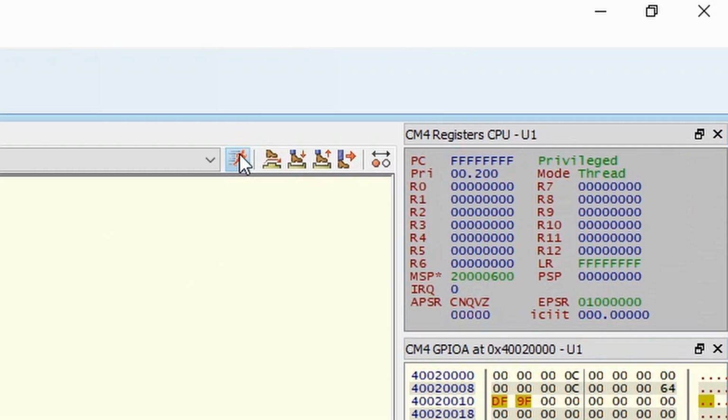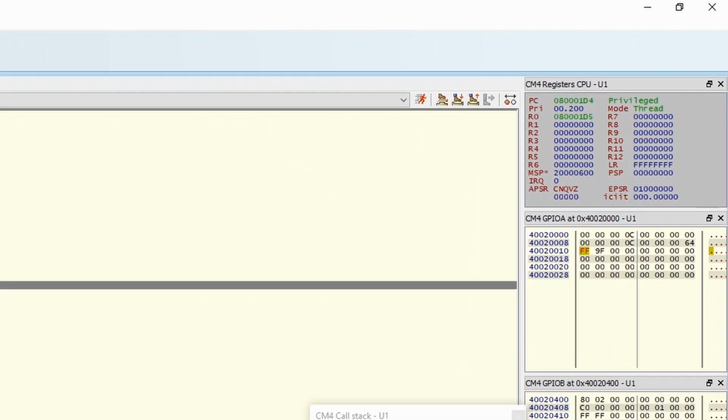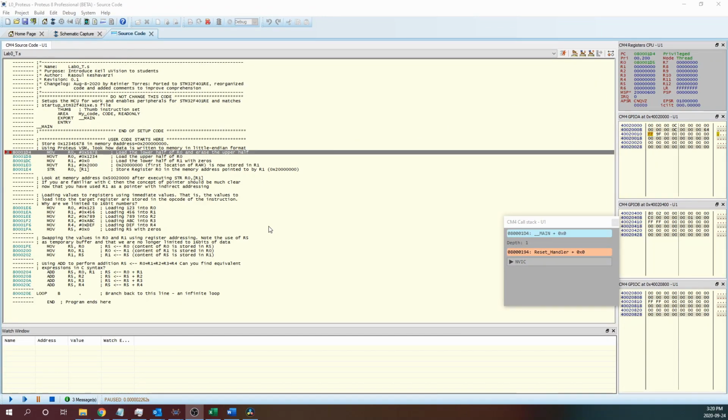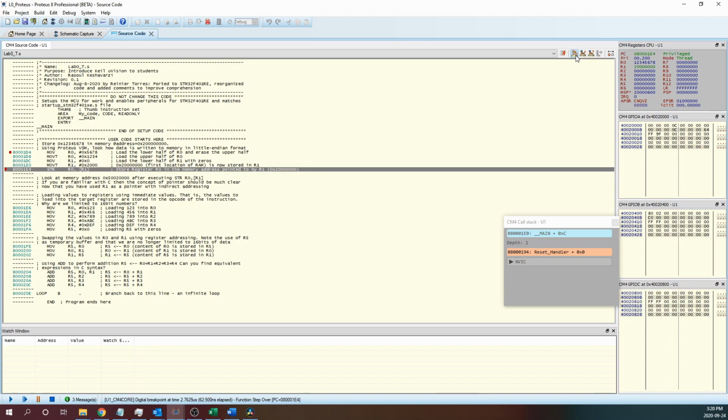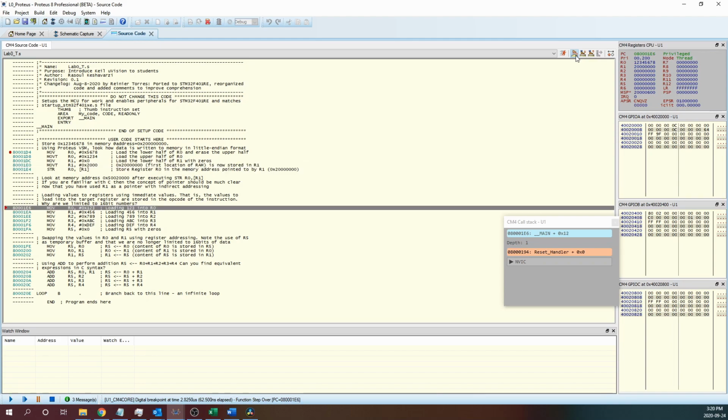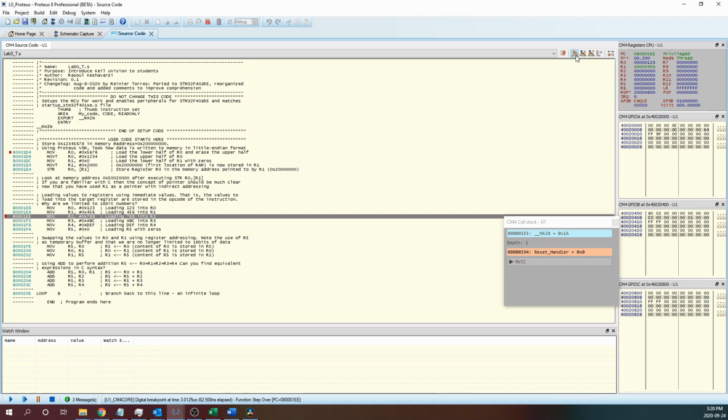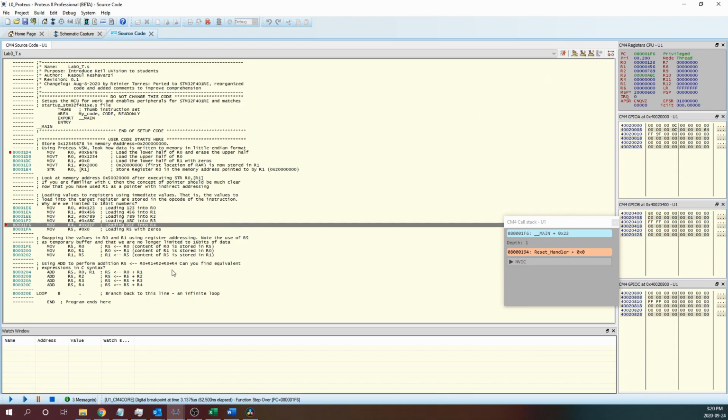To run until the breakpoint, click on the running person or press F12. The simulation will pause at the breakpoint, and from there we can start inspecting the code using the various options from the debugging toolbar. Remember that you can always use hotkeys to go faster. The debugging buttons are quite intuitive, and you can always check hotkeys and names on the debug menu.